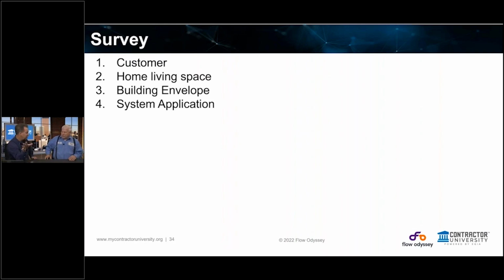So for some of the people that don't know what a knee wall is: if you've got a short wall, somewhere it's 8 foot, and then next to it it's 10 foot, like in a Cape Cod style house, right? So you've got a 4-foot wall, and then we get the slanted ceiling, where the roof deck is right on the joists. There's no attic space above it. So your second floor or third floor is smaller than the floor underneath it. What I do is take a piece of foam or something that has an air barrier so the pipes don't freeze, and I can cut down the infiltration sometimes 40-50%.